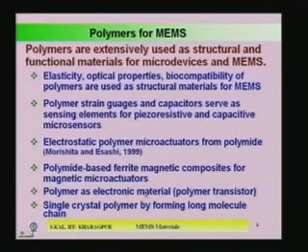Polymer as an electronic material, like semiconductors such as silicon and germanium. Similarly, polymer can be used as an electronic material because nowadays polymer transistors have come up and FETs have been successfully fabricated using polymer. People are thinking polymer can be used for active device fabrication also, so that both passive and active components and MEMS components can be integrated together, and as a whole it will be known as polymer MEMS. So, I will take one separate lecture on polymer MEMS in future.